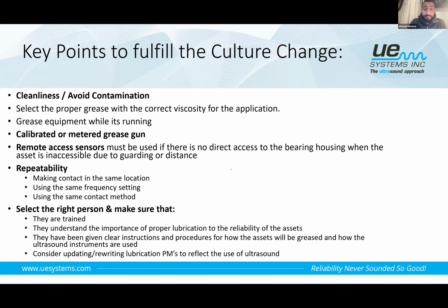It starts from cleanliness and how to avoid contamination, how to calibrate our metered grease gun, how to use remote access sensors for non-accessible bearings, and how to make sure I'm testing the bearing in the same location every time, using the same module or sensor with the same frequency settings. And also select the right person and make sure he's trained. These guys who do the lubrication for our bearings are very important.